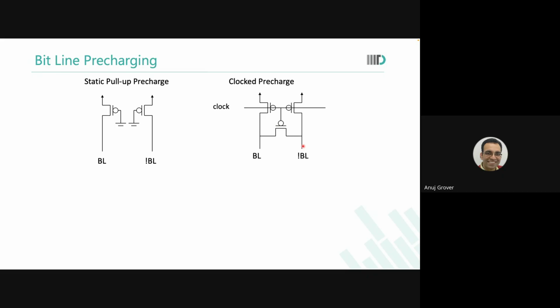That reset operation will be faster now. My next rising edge of clock can come faster. This is not a benefit on access time. There is a benefit on access time because of equalization. But what we are talking about, improving the speed of precharge after write, that is the benefit on cycle time. Cycle time, or frequency, is when can my two adjacent clock active edges come? Because my precharge happens faster, my next active edge can come faster.